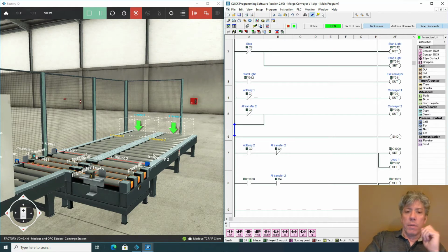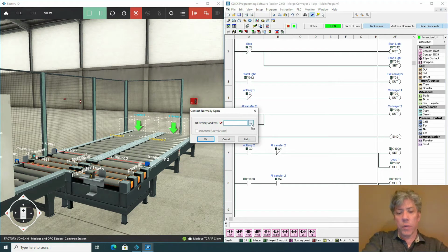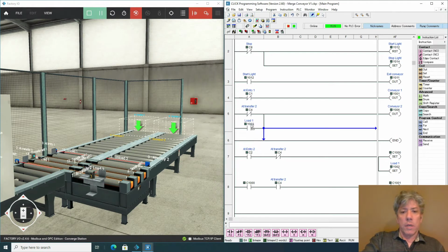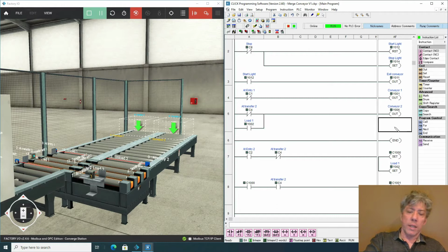The reason for that is, of course, the pallet will primarily be on conveyor 2 initially, and so if transfer conveyor 2 comes on, with not the orange strips but that little section there, it's not going to be able to grab the pallet unless conveyor 2 hands it to it. So I'm going to make an OR like I just did and say, if transfer 2 is running, which is Y2, if load is running to load transfer conveyor 2, then I need conveyor 2 to run as well. Okay?